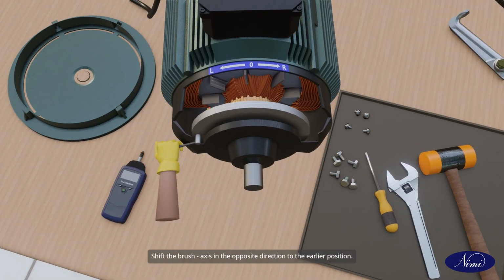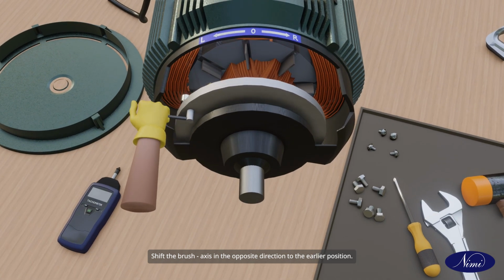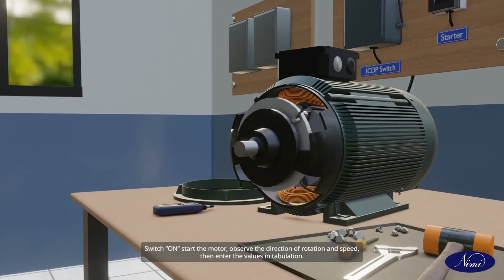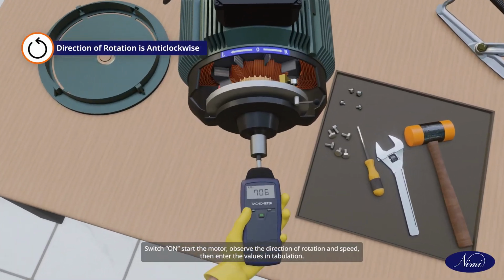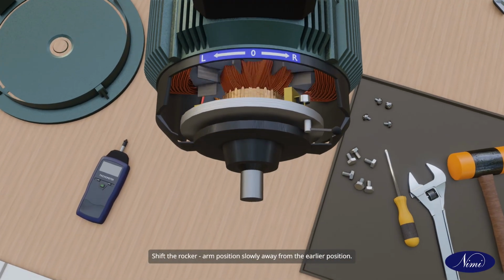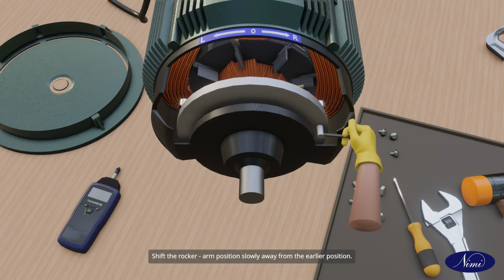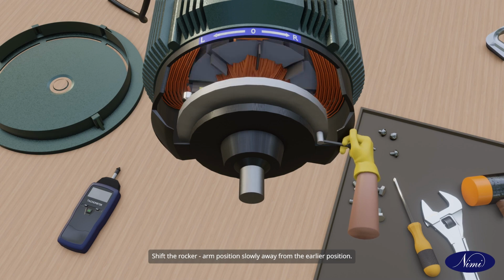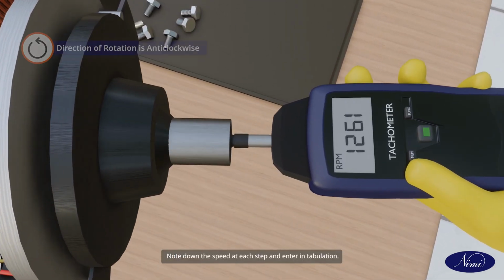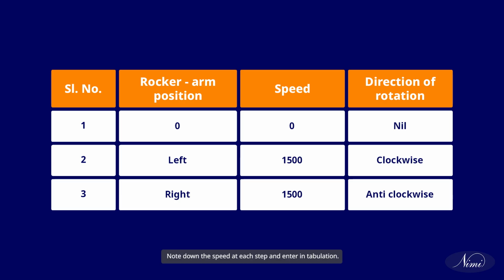Switch off the motor. Shift the brush axis in the opposite direction to the earlier position. Switch on, start the motor. Observe the direction of rotation and speed, then enter the values in tabulation. Shift the rocker arm position slowly away from the earlier position. Note down the speed at each step and enter in tabulation.